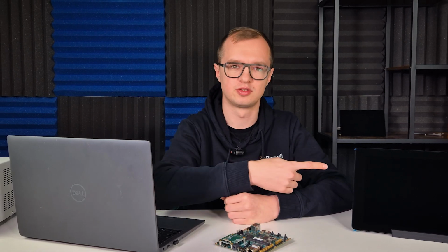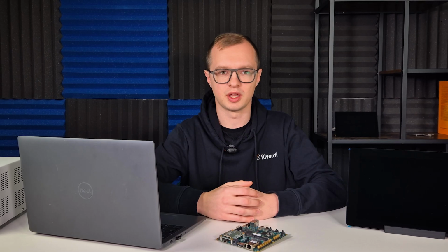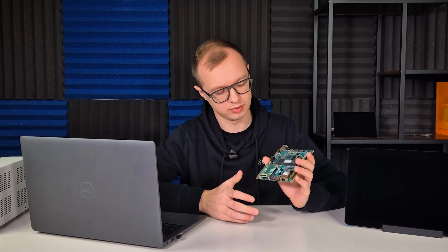And that's it for this video. We generated and configured a device tree overlay for the Toradex module so that it works properly with this 12.1-inch Riverdi display. And you can expect in one of the next videos that we will continue. With the same setup of Toradex Verdin, we will configure touch on the Riverdi 15.6-inch display.